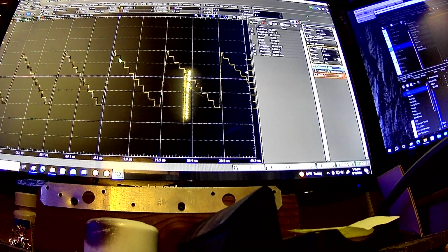But it's slew rate limited, and we saw the power bandwidth is slew rate limited too, to over 250 kilohertz. It actually is like 280 or so. You can still generate a pretty good looking triangle wave at 280 kilohertz, not half bad, 20 volts peak to peak. But anything above that is certainly going to have harmonics.